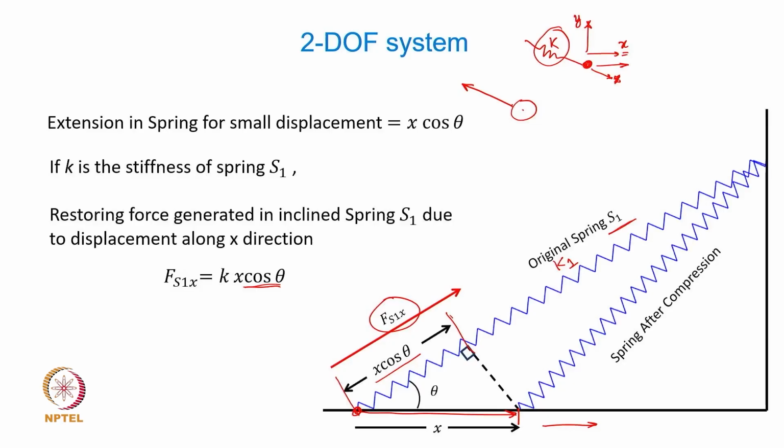If you really look at a typical spring mass system, we have discussed this, that if the spring is at certain inclination having its own stiffness k, then an equivalent spring mass system for the direction of motion along this turns out to be k cos square theta, or alpha, whatever angle that you consider.